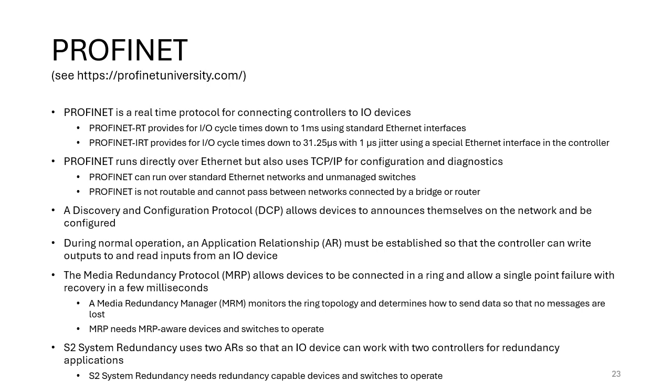So the payload could be PROFINET. And then by sending multiple packets, one after the other, you can send those multiple protocols simultaneously over that same piece of copper or fiber. So PROFINET is a standard that runs over Ethernet. It also uses TCP/IP. However, the PROFINET network part itself, the protocol, will support standard Ethernet networks.